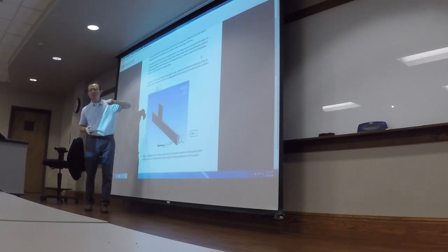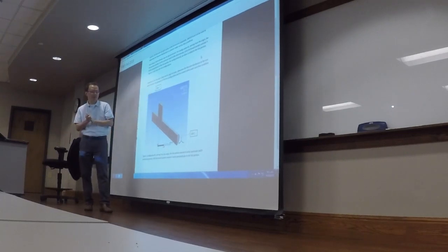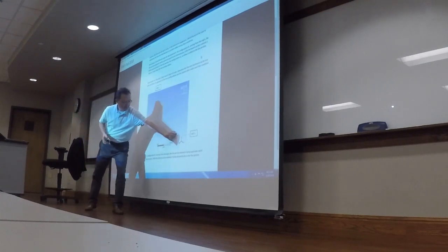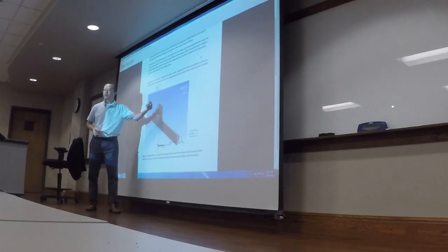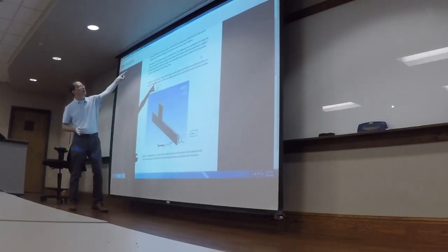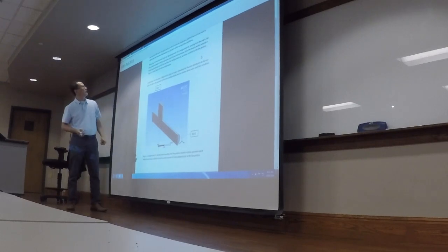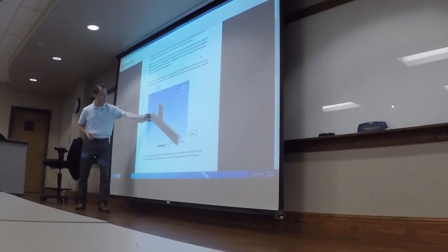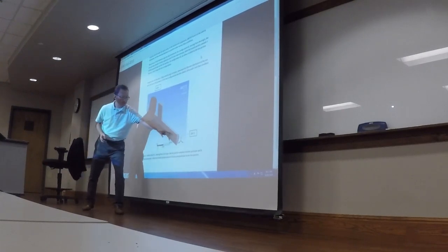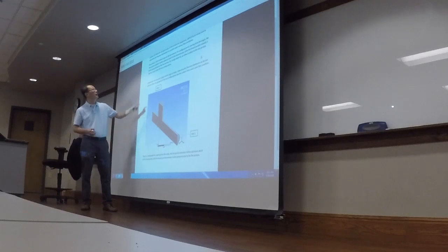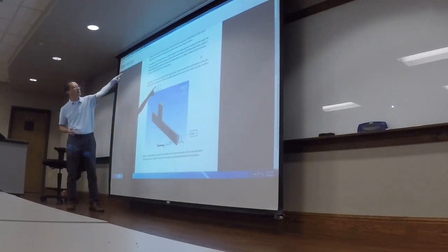For configuration number 1, we'll do two configurations. Configuration number 1. This is the T junction, this is the main flow, and this is the branch flow. Right? Starting from the origin, the line portion extends 4 inches upstream and 8 inches downstream, so the total length is 12 inches, while the branch portion extends 4 inches.